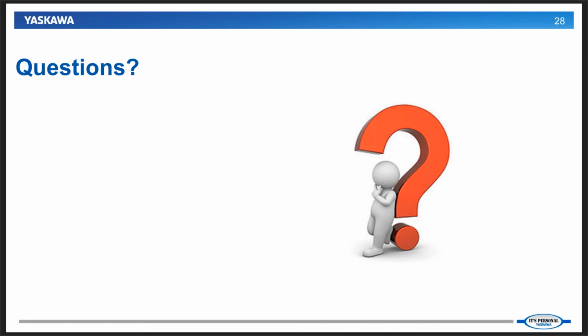And one more question. Can I use a Sigma 7 amplifier with MP2600 based SigmaLogic? No, you cannot use a Sigma 7 servo pack with MP2600 based SigmaLogic. Currently, in the market plan, there is no option for a Sigma 7 servo pack with MP2600. So if you want to use an external encoder along with extended IOs, then you have to go for MP2600 with Sigma 5 servo packs. Hope that answers your question.